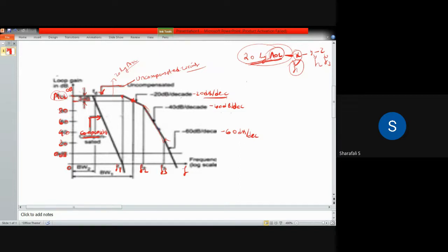From that maximum value it is going to reduce by 3 dB here, which means ACL minus 3 dB, and then here you will get the corner frequency. So if you take the frequency corresponding to that value, where the maximum gain is reduced by 3 dB, that is your corner frequency. So your first corner frequency will be at this one. Okay.